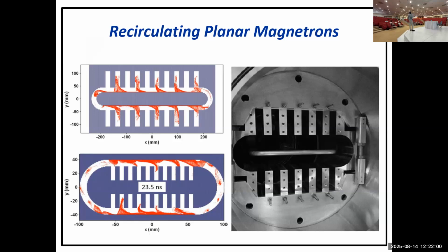Second advantage, I think there is another design. We did a BWO. I will show you a backward wave oscillator with two slow wave structures to generate two frequencies. For some applications, they need to have two frequencies in two different bands. So they have this type of two different cavity sets. Here are cavities, and here are a different size of cavities. And with one electron beam, you can generate two separate frequencies, a dual band source. So that was another advantage of doing this. Nowadays, they are working on an amplifier version of this.